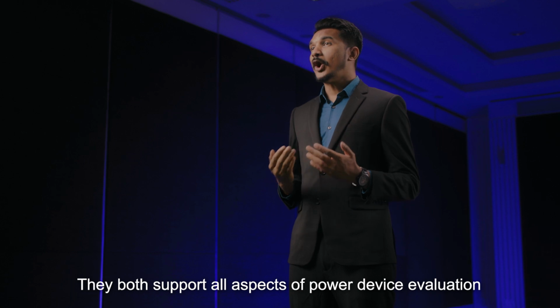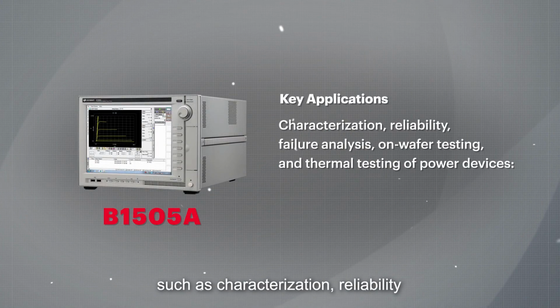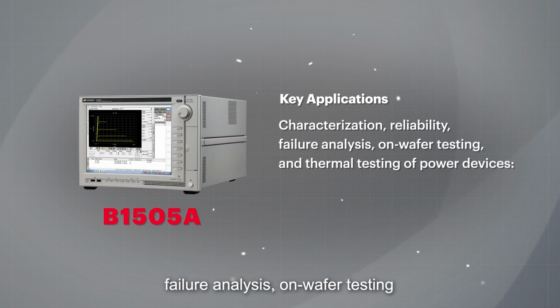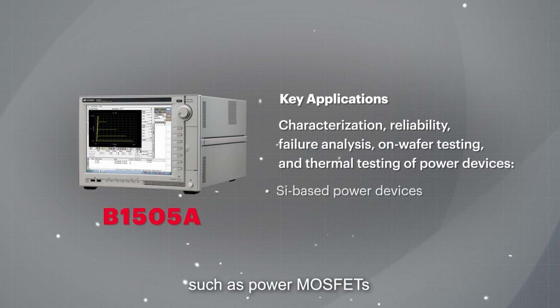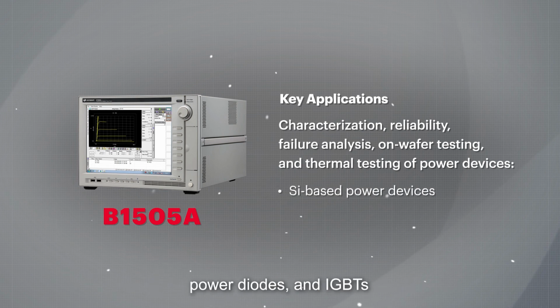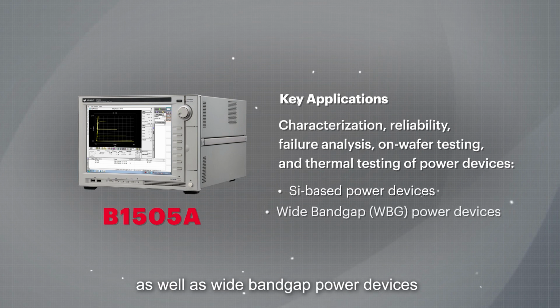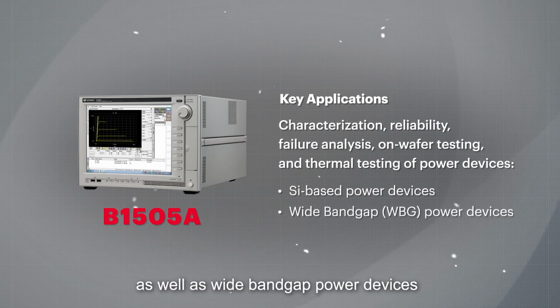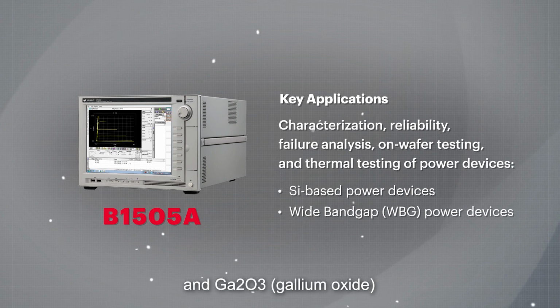They both support all aspects of power device evaluation, such as characterization, reliability, failure analysis, on-wafer testing, and thermal testing of silicon-based power devices such as MOSFETs, power diodes, and IGBTs or insulated gate bipolar transistors, as well as wide bandgap power devices such as gallium nitride, silicon carbide, and gallium oxide.